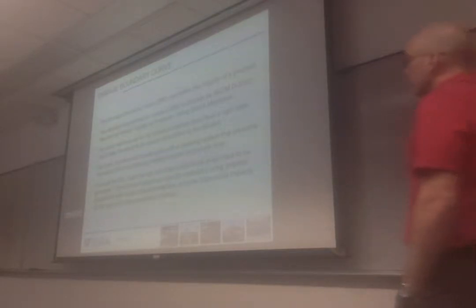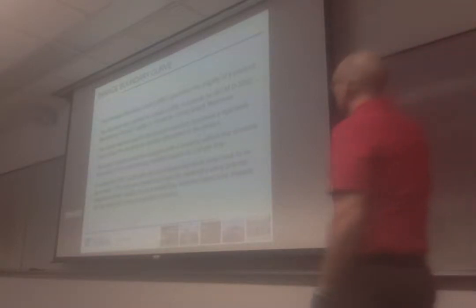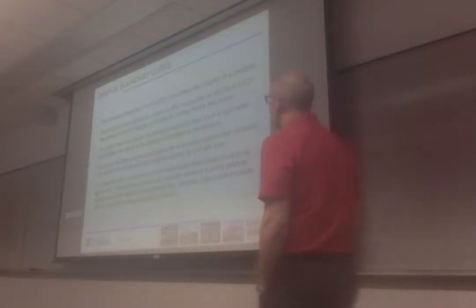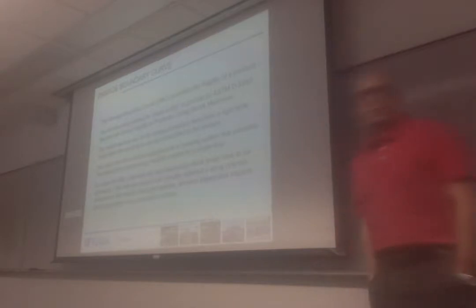Now we're talking about shocks, and in this case we have to look at what kind of impact damages the product. So this is based on the ASTM standard. We're going to talk more about ASTM standards later, but that standard is D3332, and it's titled Mechanical Shock Fragility of Products using Shock Machines.